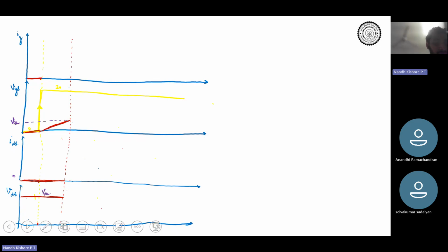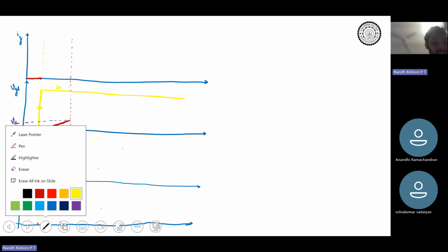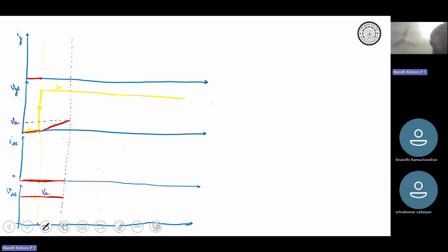So what happened was, we know that peak gate current would happen here, right? So this is the instant at which the capacitor is totally uncharged and you have a VGS that is happening, that is, you have VG going from 0 to 20. Okay. So there will be a peak gate current at this particular instant. Okay. So let me call this IG peak.